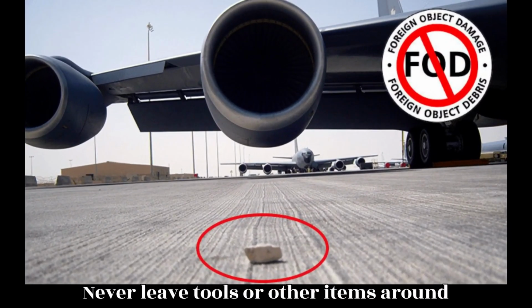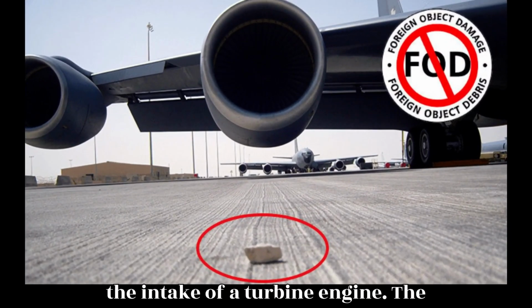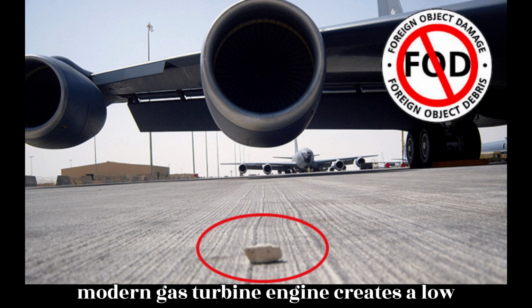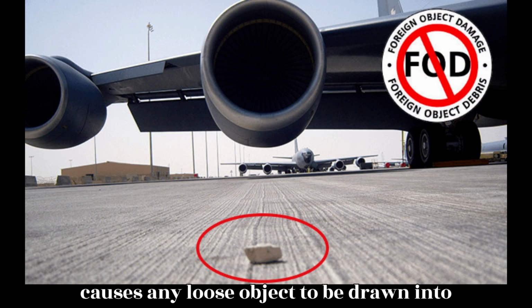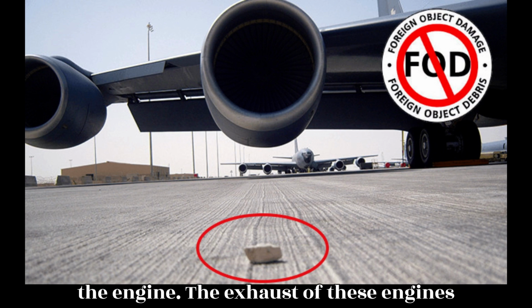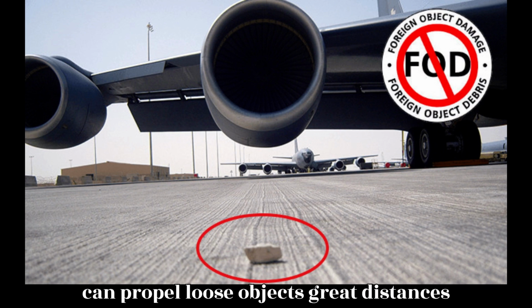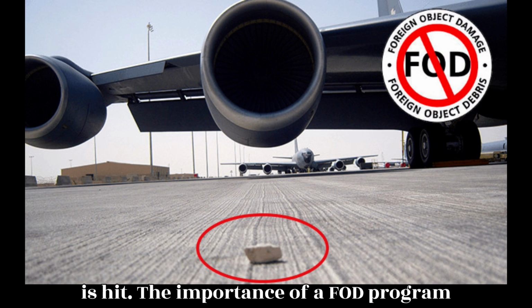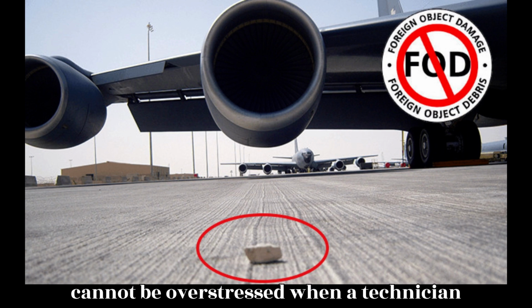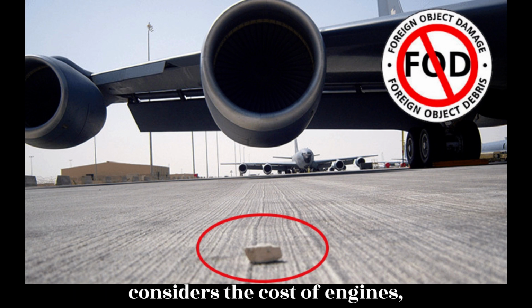Never leave tools or other items around the intake of a turbine engine. The modern gas turbine engine creates a low-pressure area in front of the engine that causes any loose object to be drawn into the engine. The exhaust of these engines can propel loose objects great distances with enough force to damage anything that is hit. The importance of a FOD program cannot be overstressed when a technician considers the cost of engines, components, or a human life.